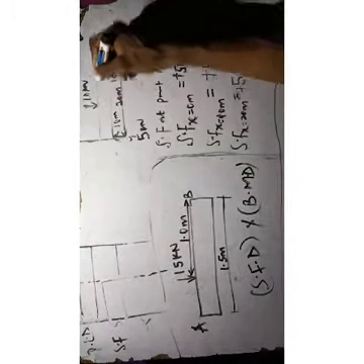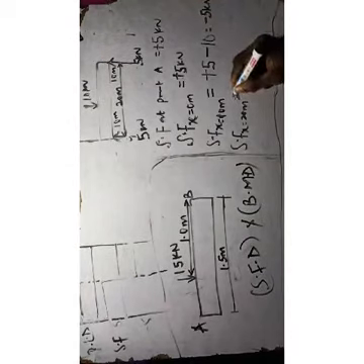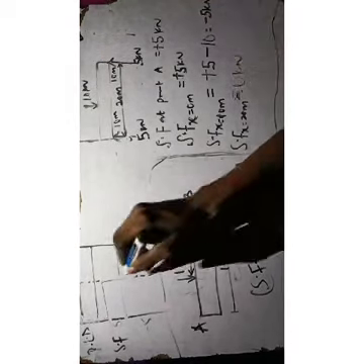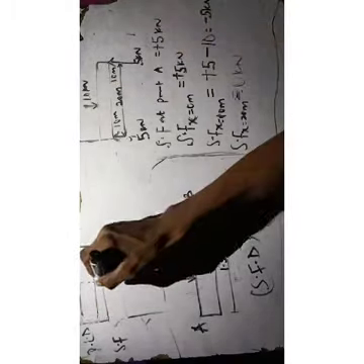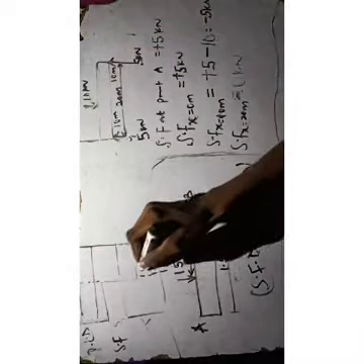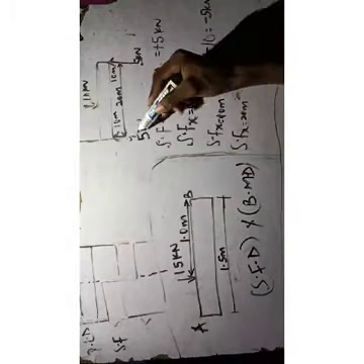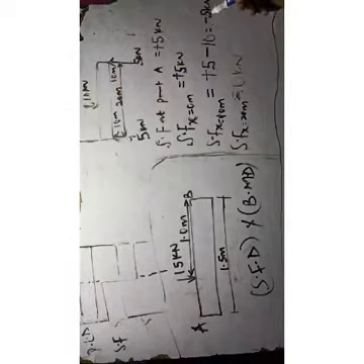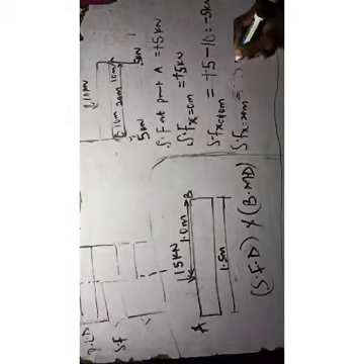It's constant again and drops back to 0 kilonewton. That is, from here plus 5 constant, it drops to minus 5. So my minus 5 is here, then constant again to 0. So it's constant and goes back to 0. This 0 here is obtained from your 5 minus 10, that is minus 5, and minus 5 kilonewton plus 5 equals 0.